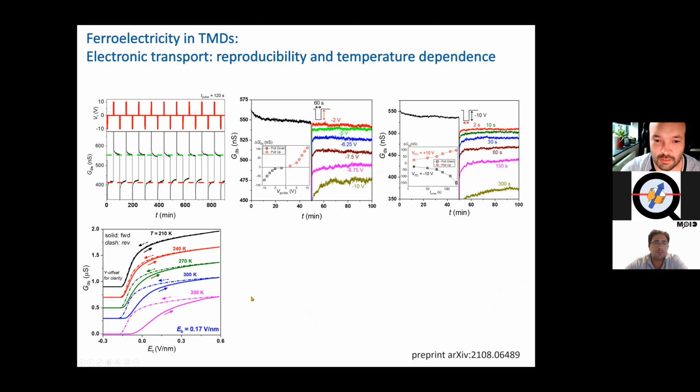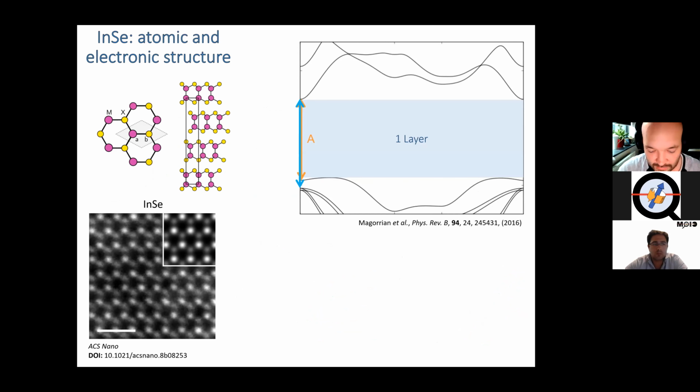Right, so from this, if I do have 10 minutes, I'd like to show some other results that we had, and they are to do with another material, a 2D semiconducting material that we worked on. It's called indium selenide, monoselenide. There is a big difference between indium 2 selenium 3 and indium selenide. They are both semiconductors, but this one has pretty high quality. So the mobility, just to give you some numbers, at cryogenic temperatures is about 15,000, and there are now better crystals where mobility is getting higher. So it is an interesting material, a new system to study.